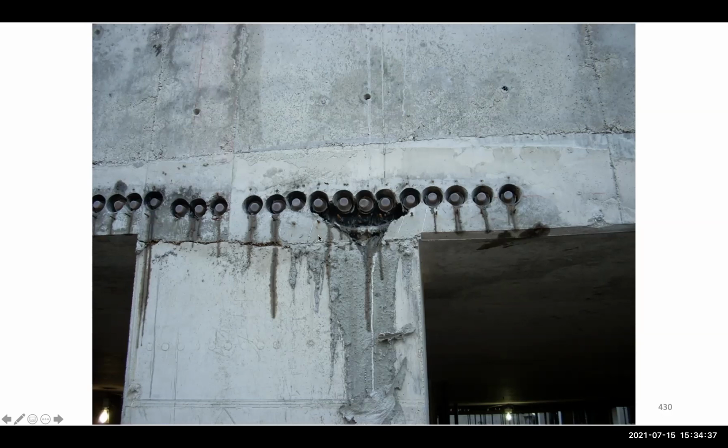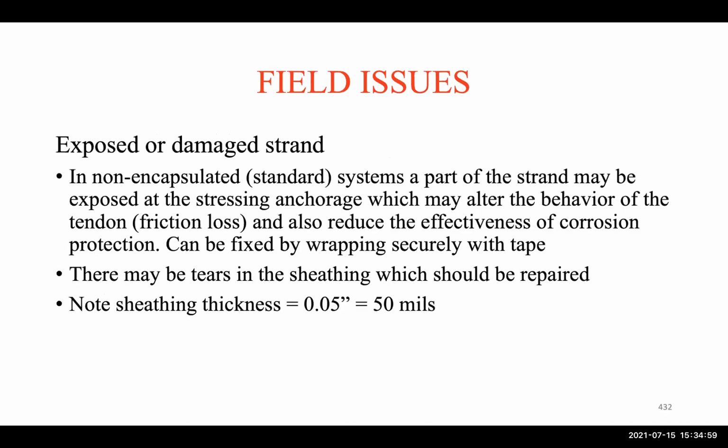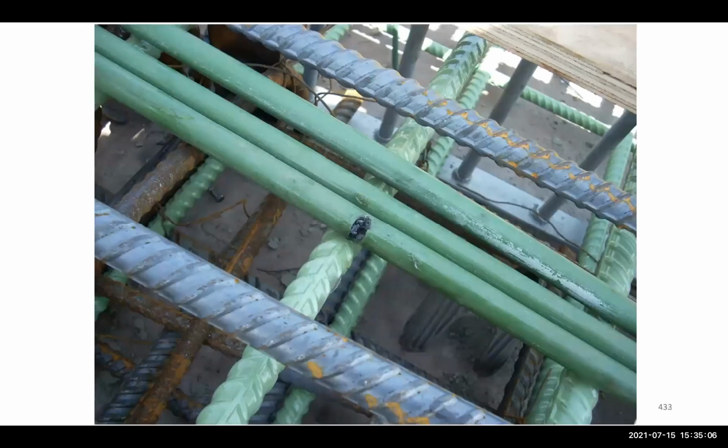Why do we have that? And this shouldn't be left like this because it will cause corrosion. Observe if couplers are adequately used. If couplers are used, then we have to make sure that they are used properly. Exposed or damaged strand.